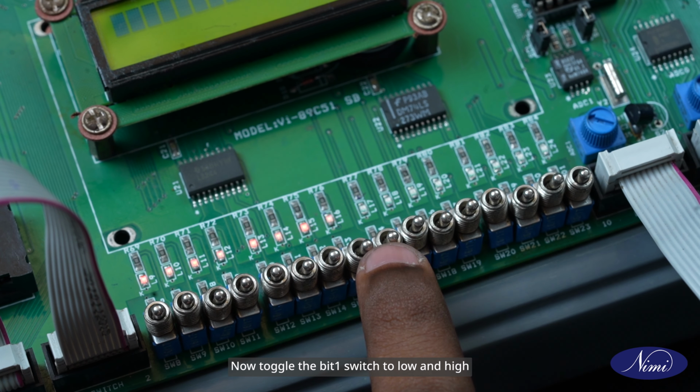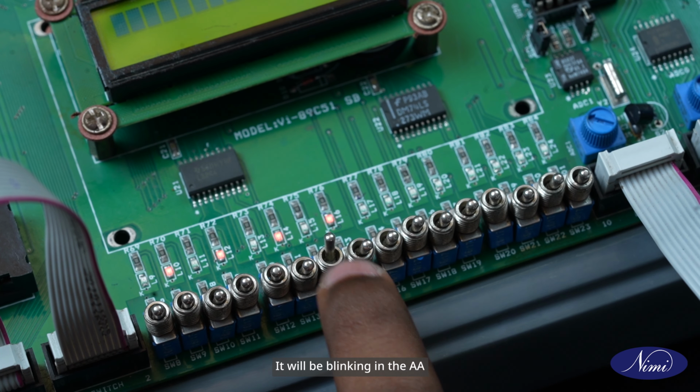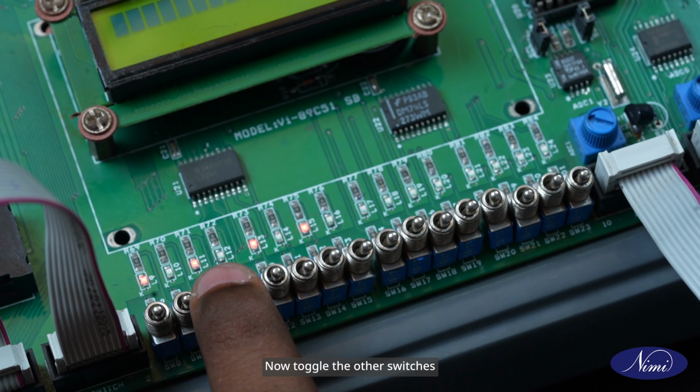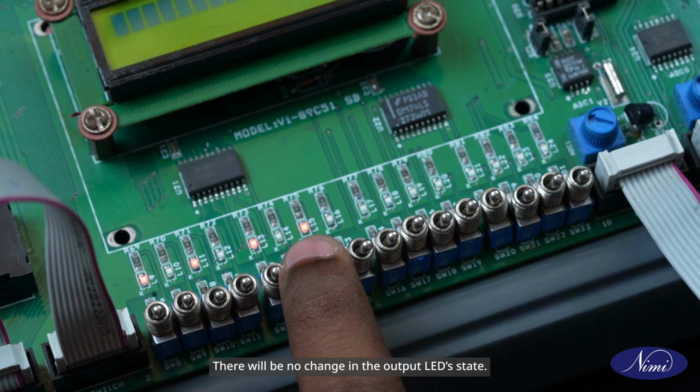Now toggle the bit 1 switch to low and high and see the LED. It will be blinking in the AA and 55 patterns. Now toggle the other switches. There will be no change in the output LED's state.